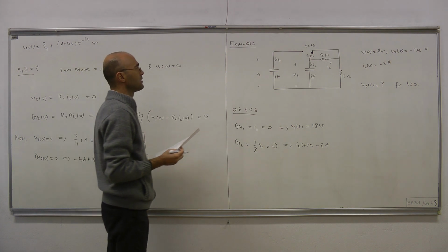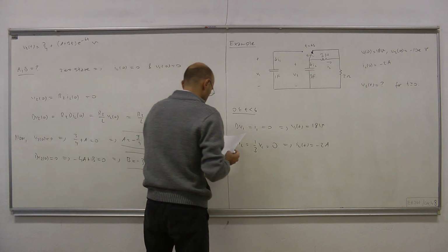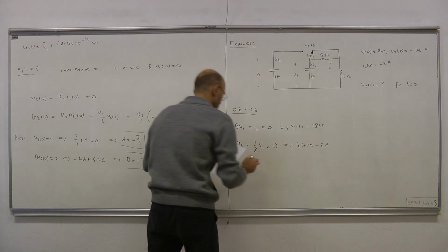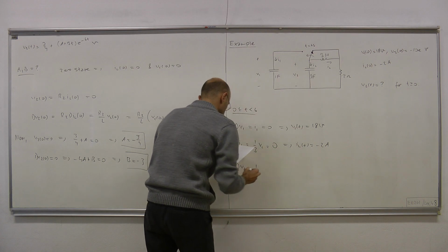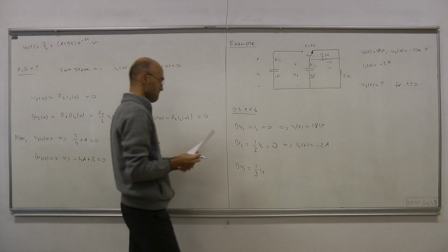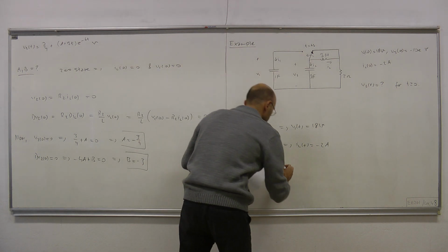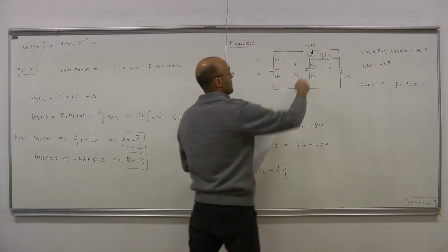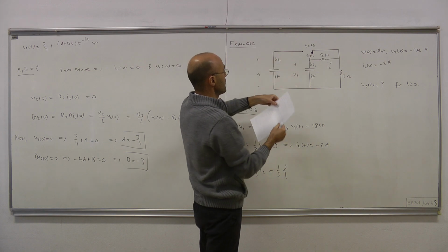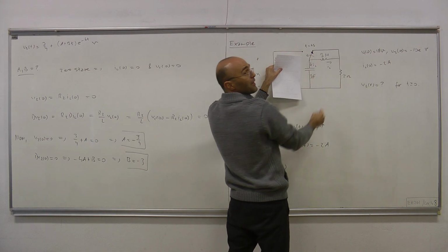And how about our third dynamic component? Second capacitor, dV2 equals 1 over C times I2. That equals 1 over 3. Okay, so this is I2. This is open circuit. There is no current, therefore we can forget about this branch here. This I2 flows over the resistor in that direction.